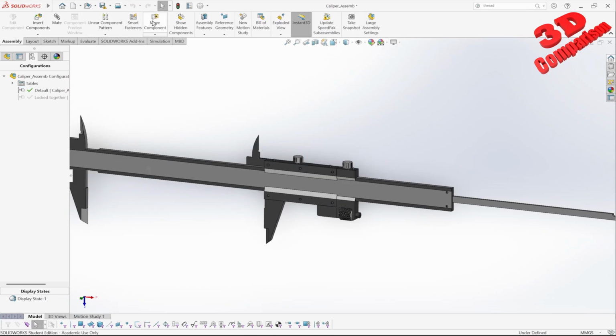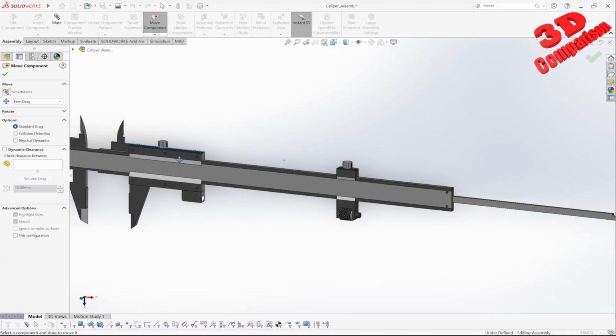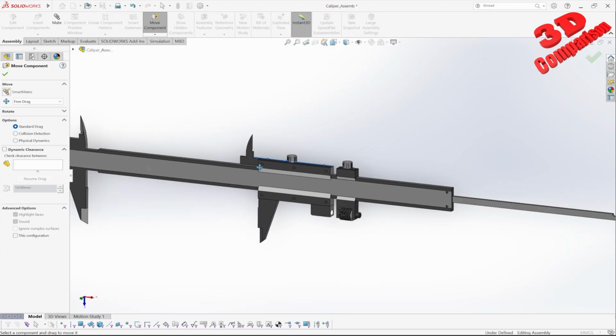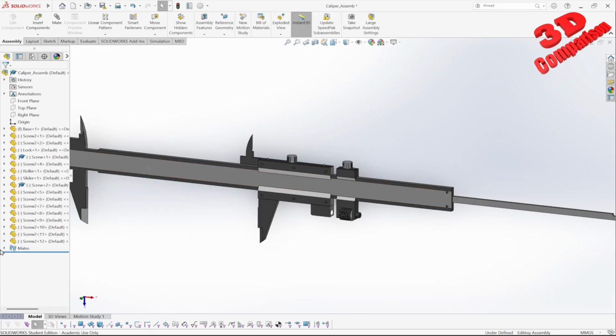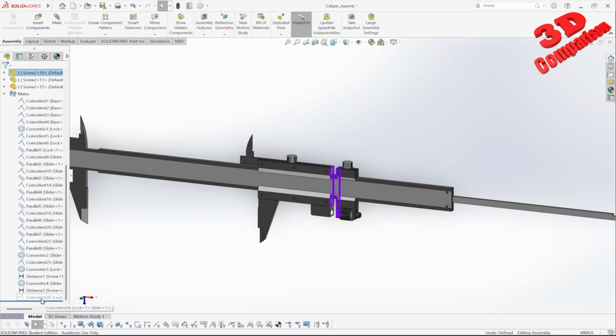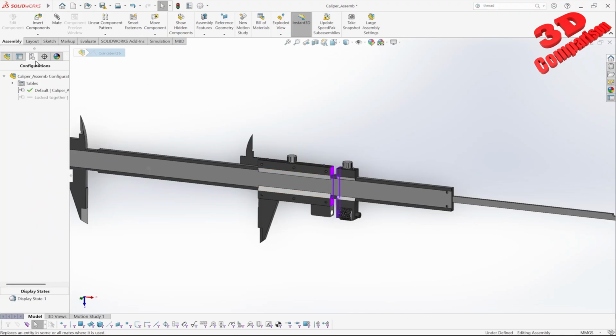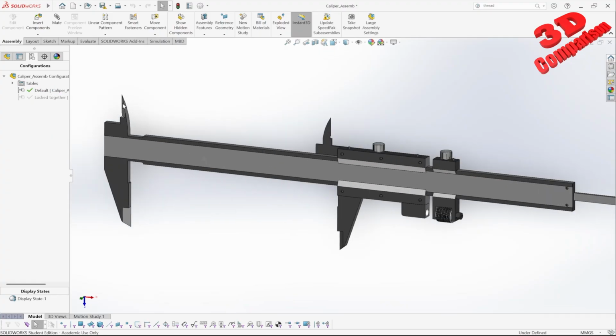And what actually happens over here, if you also check my previous video regarding configurations for the hinge, if not, I highly recommend to do so. If I'm going to go within mating, we're going to see that in this case, this coincident will actually be disabled. So I don't have to manually go and have it suppressed, because that configuration will just do that over here. So I have those well defined over here.